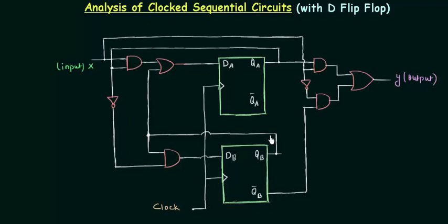are three steps involved for getting the state diagram, and we will see each step one by one. It's not a very tough thing to do once you have the basic idea or once the steps are clear to you. So without wasting any time, let's move to this circuit. In this you can see the input is X, the output is Y, and two flip-flops are used, and both the flip-flops are D flip-flops, and also gates are used as our combinational logic, the input combinational logic and the output combinational logic. So the first step, let me write it down.